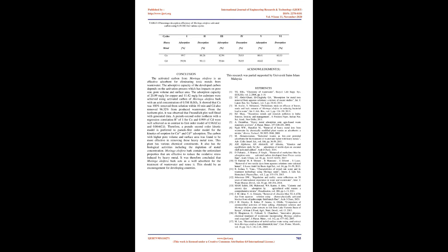Desorption of heavy metals. The reusability of Moringa oleifera was studied by a cycling adsorption/desorption process, with C0 equal to 5 mg/L, pH 11, S/L equal to 0.25 g/L, time equal to 60 minutes, and temperature equal to 25°C. The studies were conducted by a batch desorption technique using HCl, H2SO4, NaOH and Na2CO3 of 0.1 N with the metal-loaded adsorbent, as shown in Figure 13 and Table 4. Hydrochloric acid performed great desorption efficacy for Cu2+, 88.26%, and Cd2+, 99.13%.